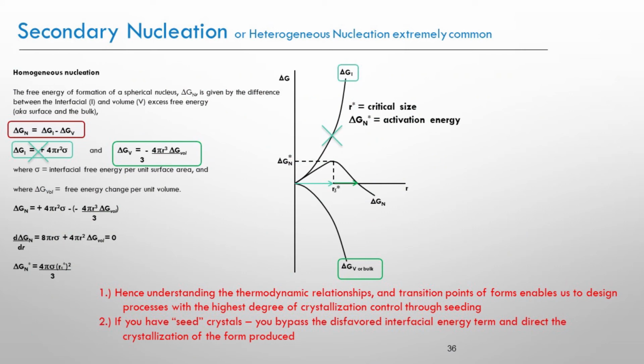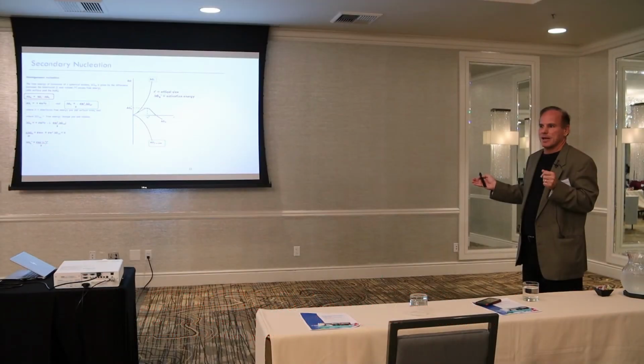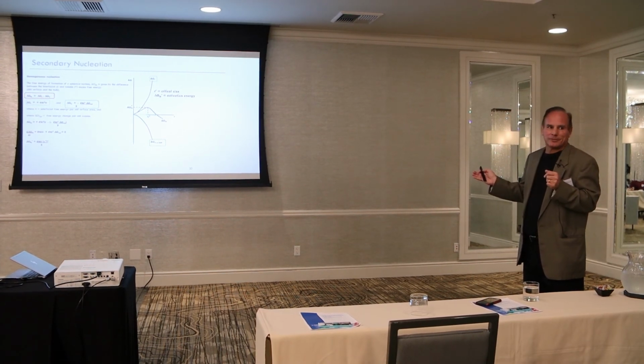But some people say primary nucleation doesn't exist. I've heard that before from some pretty good scientists. But secondary nucleation, whether you consider it by seeds, is something we use to our advantage in processes. It'd be preferable that you wouldn't have to use seeds, but it's your best way to control crystallization of a process. And it's always prudent to write in a seeding step.